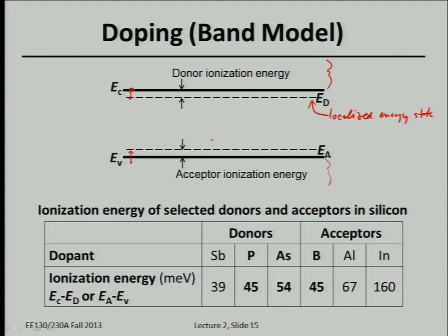So when you process a semiconductor device, if the devices become very small, that means they have to become very small, not only in lateral dimensions, so you can fit many of them on a chip, but they have to become very shallow in doping profile. So you really don't want dopants that you introduce to diffuse into the silicon too far. Indium has a relatively low diffusivity, so it won't move far from where you place it. So it's desirable for that reason to be used in integrated circuit devices today. But anyway, the answer to one of your homework problems: boron and indium are the common p-type dopants. In other words, they introduce positively charged carriers into your semiconductor sample.